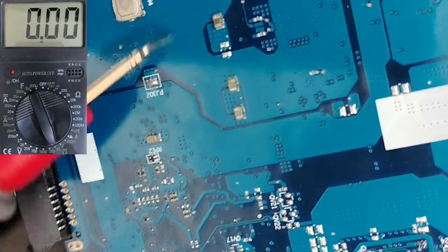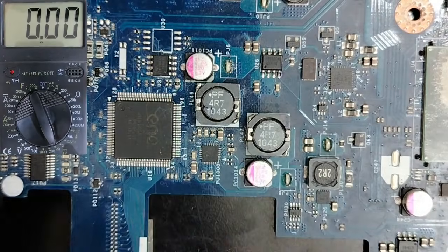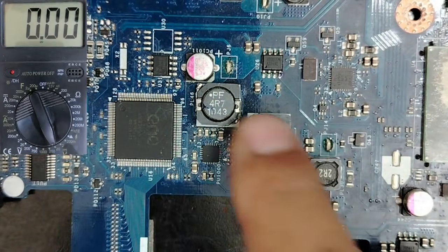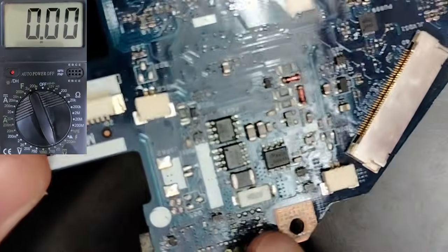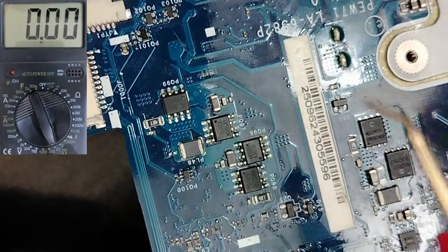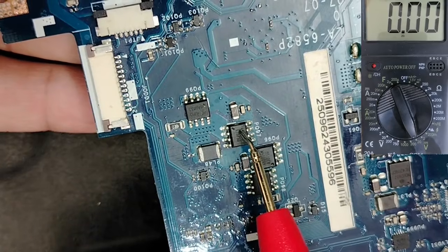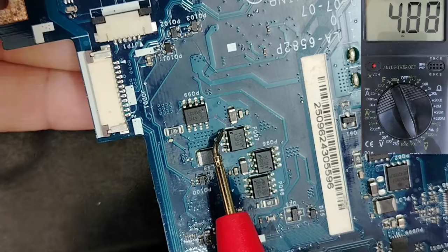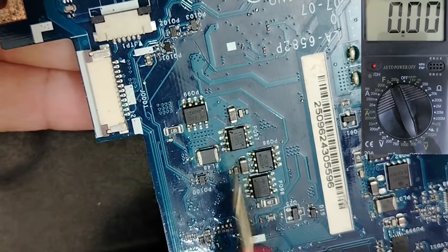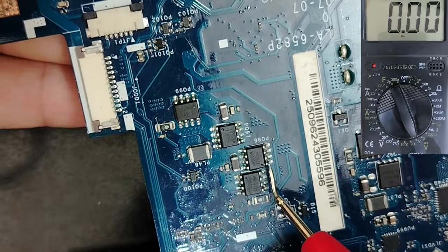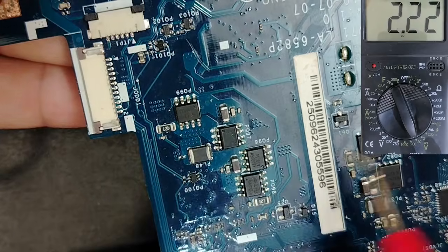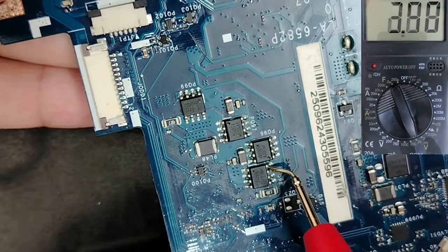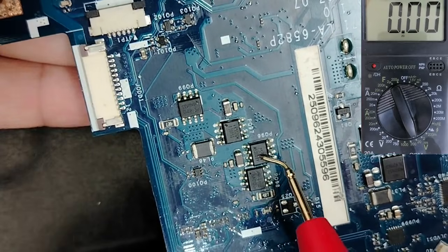We don't have MOSFETs there. Even if we check the back, do you see, we don't have MOSFETs. But for this one over here, we have 4 MOSFETs on the back. Let's check the back, exactly the back over here. Let's check, guys. Do you see? We have 4 MOSFETs. So these 2 MOSFETs, as you can see, are for the 5 volt channel. We can even check here. We have 5 volt. Here also we have 5 volt because these 2 MOSFETs are connected. For those MOSFETs also, let's check here, guys. We have 3.3 volt. On this side we also find 3.3 volt because these 2 MOSFETs are connected.